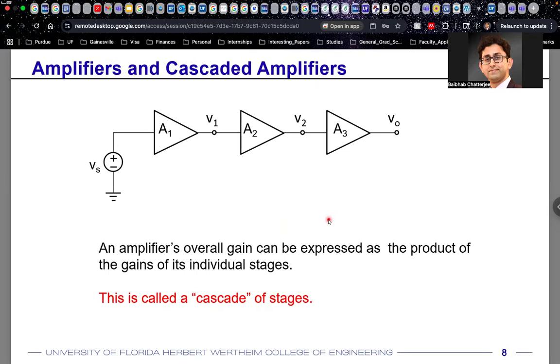And eventually the gain might even become zero when this curve flattens out. Because the slope of this curve, when it is flat, is zero, right? And the gain is basically the slope of this curve, the output over input. If you plot that, the slope of that curve will be your gain A.